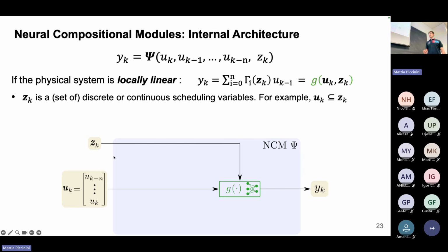But then a single linear system is not enough to describe the nonlinear dynamics of the car. Maybe there is no linear drag, no linear effects. So we still need to use the speed as a scheduling variable as well. Maybe the system is linear from 20 to 40 kilometers an hour, and then also from 40 to 60, but it's linear in a different way.